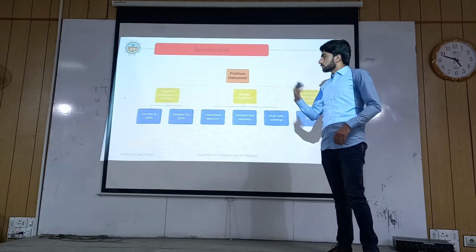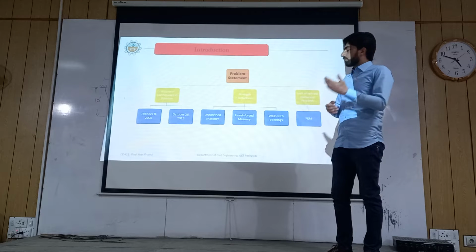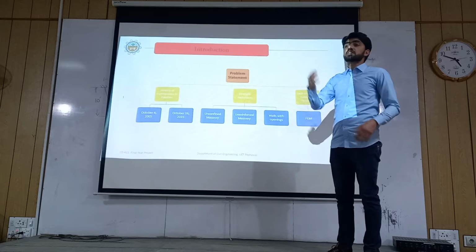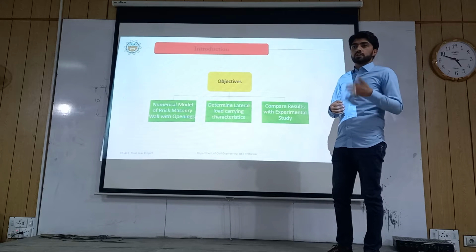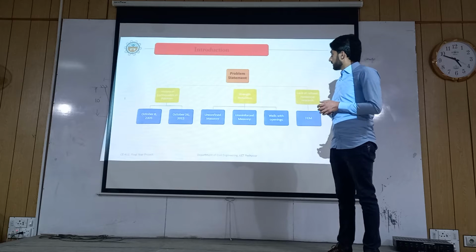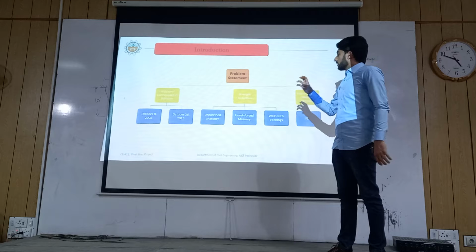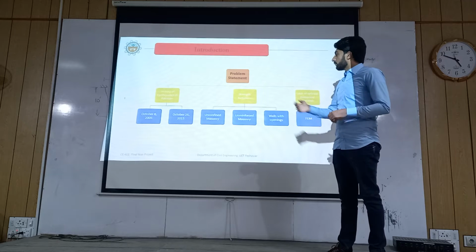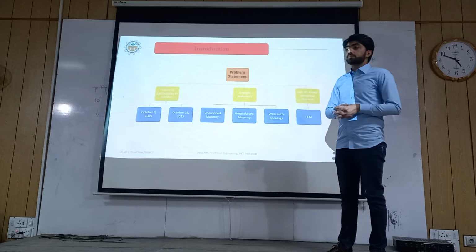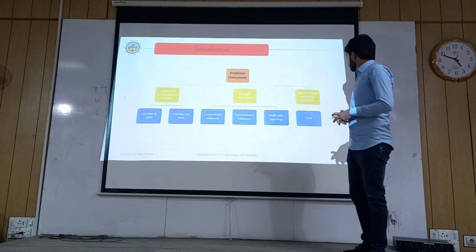Most of the structures that were partially damaged or collapsed, when studies were carried out, were of brick masonry. Most of them were unconfined and unreinforced masonry. These factors affect the strength of brick masonry: unconfinement, unreinforcement, and walls with openings also affect the lateral load carrying capacity of brick masonry walls.